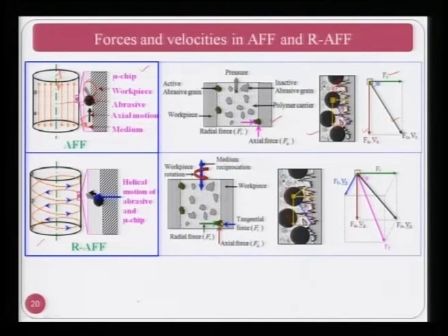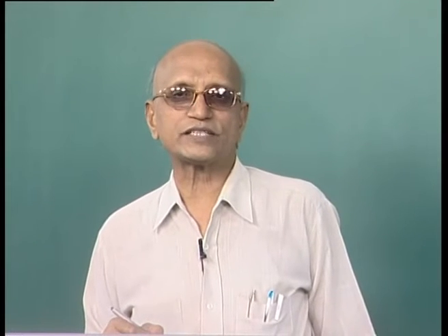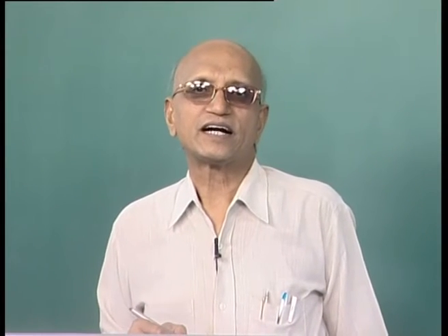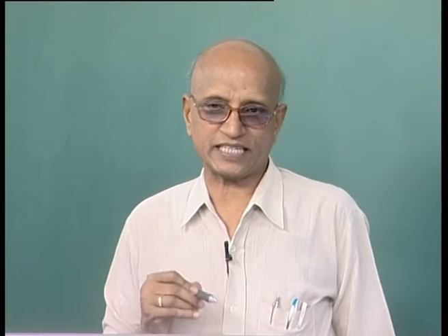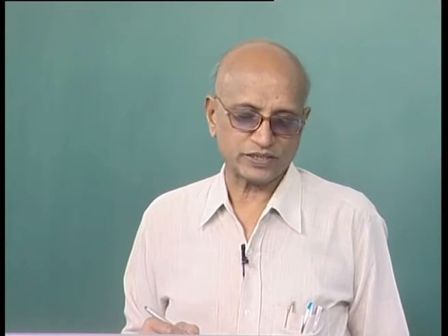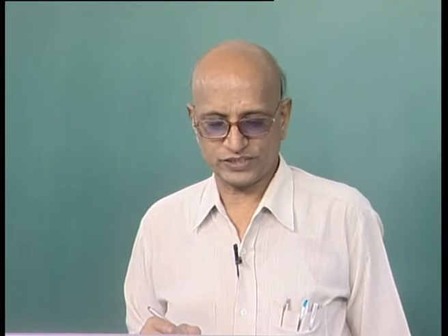As a result, the total length of travel of an abrasive particle along the workpiece surface increases substantially compared to the abrasive flow finishing process. As a result of this, it is shearing more peaks from the workpiece surface, or you can say the finishing rate is improving compared to abrasive flow finishing. This is the gist of the whole rotary abrasive flow finishing process.